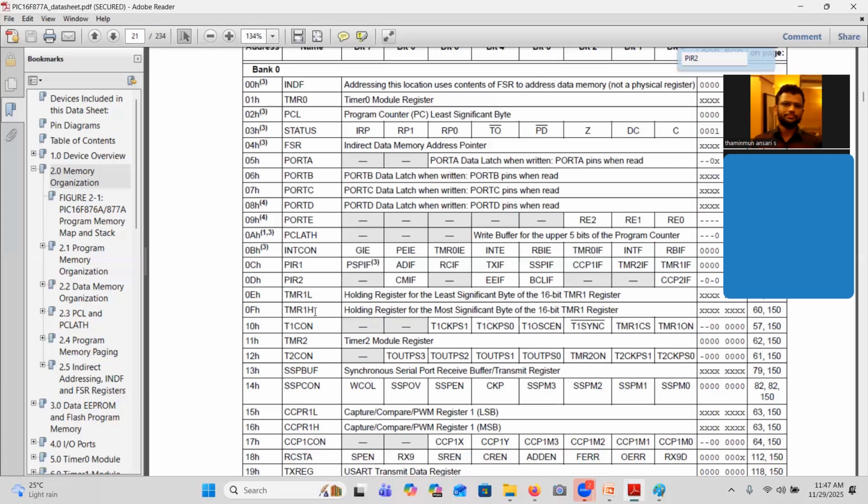So the timer will be slower than the microcontroller. Okay, how to make the timer slow? For that, they have two bits, the timer clock prescale bits: timer clock prescale 0, timer clock prescale 1. What will this do, let us explore.